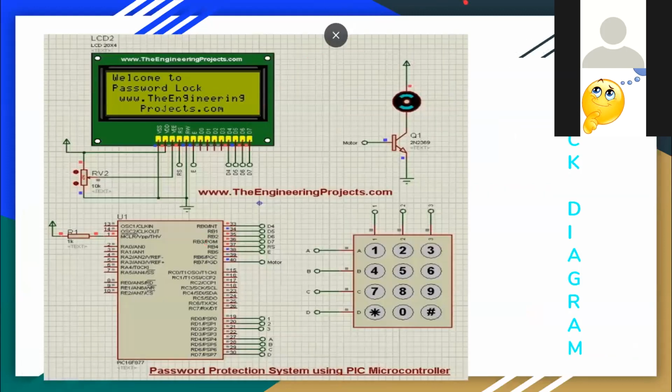This is the block diagram. Here we use the LCD along with the keypad, motor, then PIC microcontroller. We also use a transistor, which is a kind of driver for the DC motor, because the DC motor is operated at 12 volts, while the PIC microcontroller signal is 5 volts. So we need this transistor in order to drive our motor.